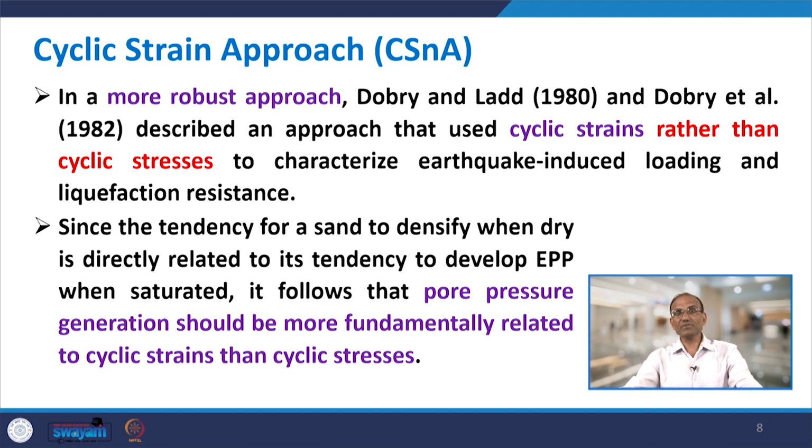The tendency for a sand to densify when dry is directly related to its tendency to develop excess pore pressure when saturated. In fact, there is an analogy between the saturated sample and the dry sample. In the case of a dry sample, when you do the loading, there will be development of volumetric strains.